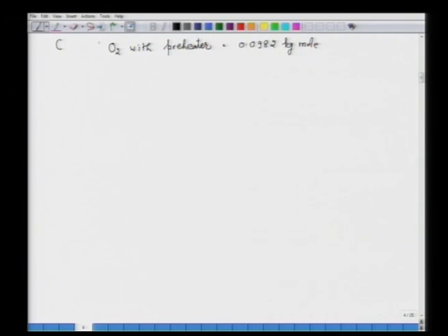Now, you have to recalculate the products of combustion. Now, theoretical oxygen would be equal to 0.0705 kg mole, that we will be calculating from products of combustion which has CO2 and oxygen.